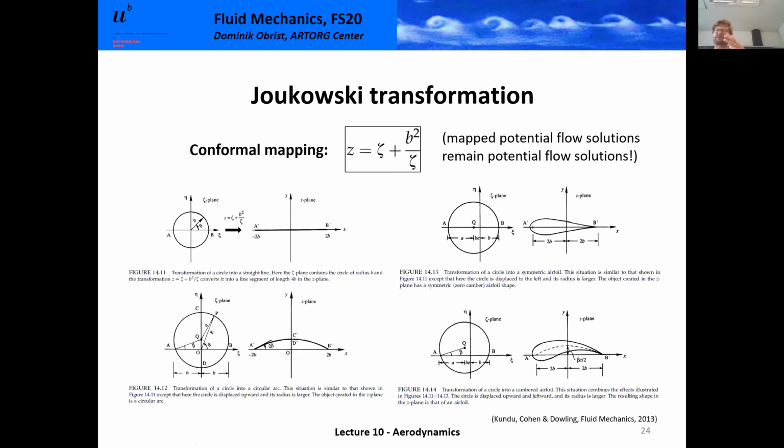And so this is a way to parameterize a whole family of airfoils, and this family, surprise, surprise, is called the Joukowsky family of airfoils, Joukowsky airfoil, which you can parameterize quite easily, and you get a large range of airfoils. So now why is this useful, this conformal mapping or this Joukowsky transformation?